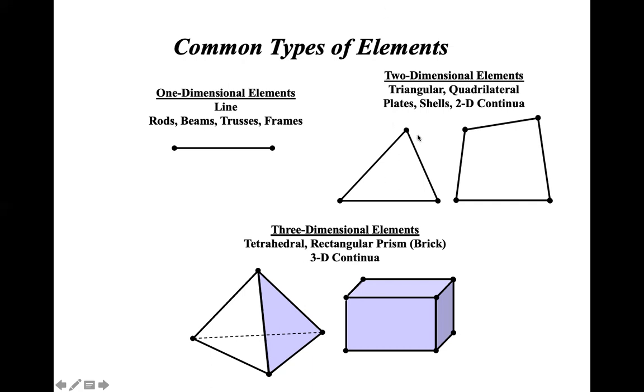Now, if you have a very complicated geometry, and in that all the dimensions, like thickness, length, and width, are important, like none is negligible or small, in that case we have to consider solid elements. And the solid elements may be tetrahedral, rectangular prism. There are different types of solid elements that we can consider.